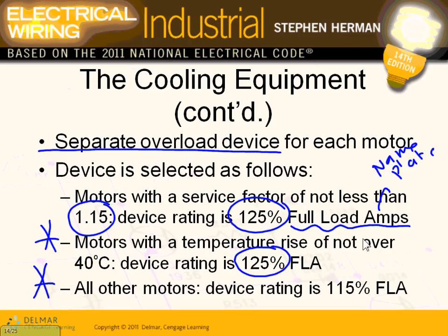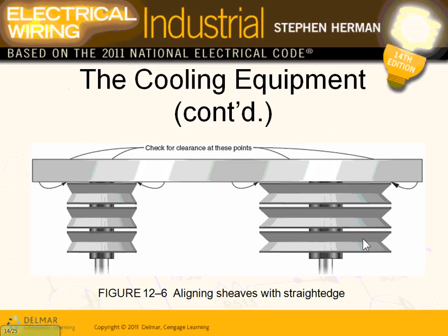In other parts of the world or other locations, they might have one device that provides overload and overcurrent protection. So if you have one device that gives you overload and overcurrent protection, then you size this by 1.25. Typically we don't encounter this here.